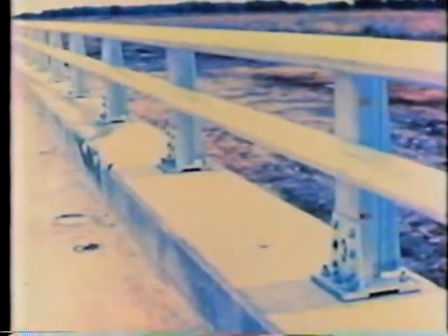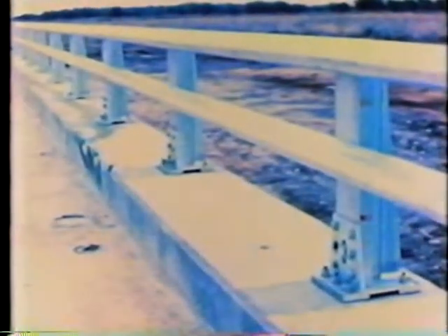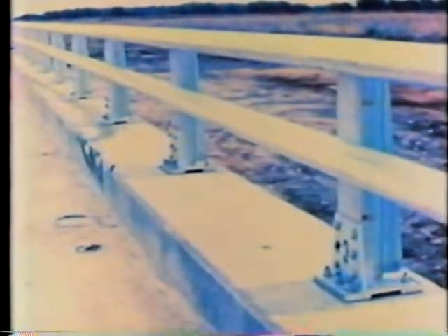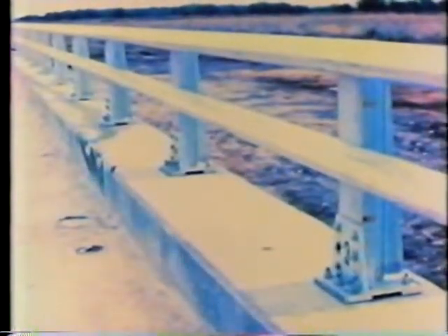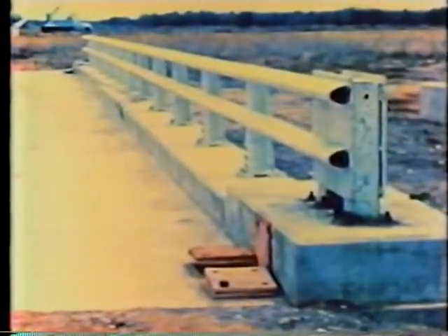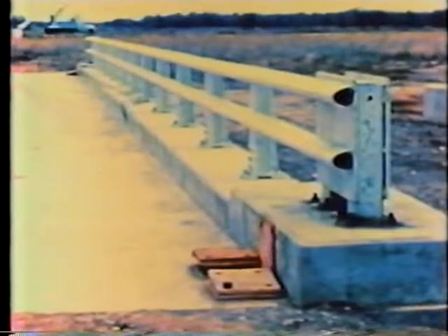This aluminum railing is mounted on a brush curb and has 2 rails. The height of the railing is 38 5/8 inches, including the brush curb. The test vehicle hits at a 15-degree angle. There is tire scrubbing on top of the brush curb and tire snagging on the posts, causing a rollover. This lower rail was 4.5 inches too high, which surely contributed to the snagging. This is a tubular thri-beam railing, 33 inches high, mounted on rigid steel posts. It is a success at redirecting the test car.